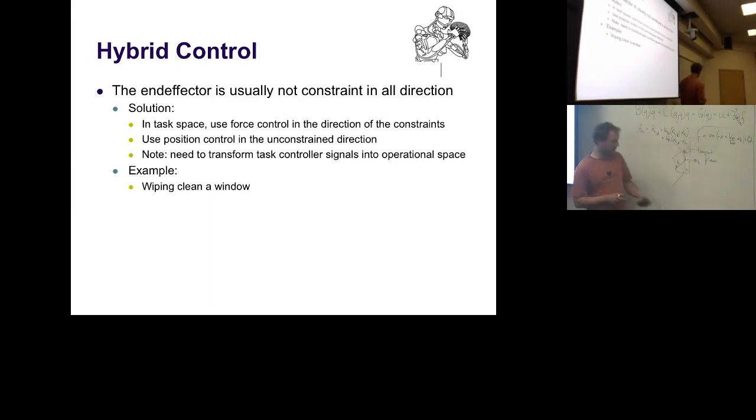And now the only thing you have to do is, given that the x, y, z of your end effector will not coincide with this normal and tangent space, you have to have one coordinate rotation between the two of them to relate them to each other. So unfortunately, coordinate transformations matter. Sorry, it's annoying. But these are all the things you have.